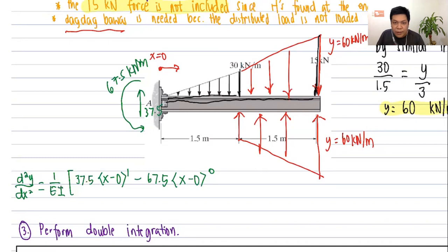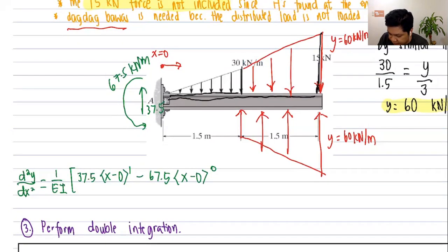Next, how about the triangular load that is downward? So going back to our lecture from last meeting, it should be m over 6, where m is the slope. The magnitude is negative because it's downward. M over 6, m is the slope. So to get the slope, it's rise, this height, divided by the width over here.